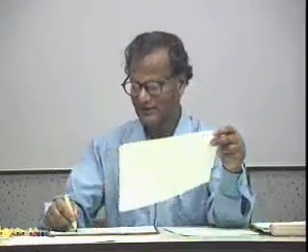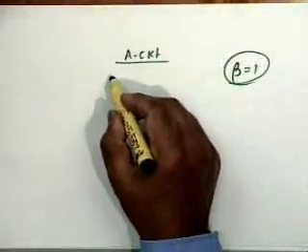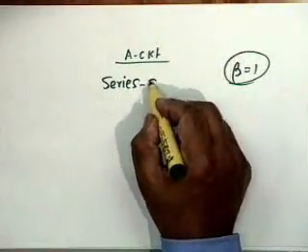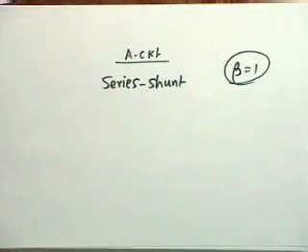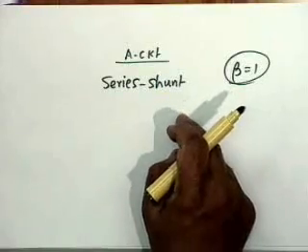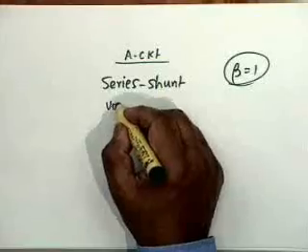It is also obvious that beta, in this case, we don't have to do anything. What is beta? Beta is 1, because V0 prime will be equal to Vf prime. There is only a shunt resistance across it. So, one thing we identify immediately is beta equal to 1, and the connection is series shunt. Now in series shunt, what should be the model of the amplifier? That determines the drawing of the A circuit. What should be the model of the amplifier? Voltage to, no, voltage to voltage. Don't make such mistakes. This is a voltage to voltage.